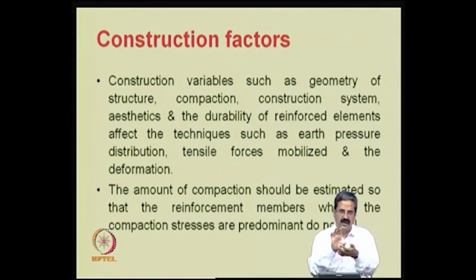The dilation tendency will induce more effective stress. So you have some existing effective stress plus the effective stress component due to the dilation tendency, which is not allowed to take place. So that extra pressure is also added.